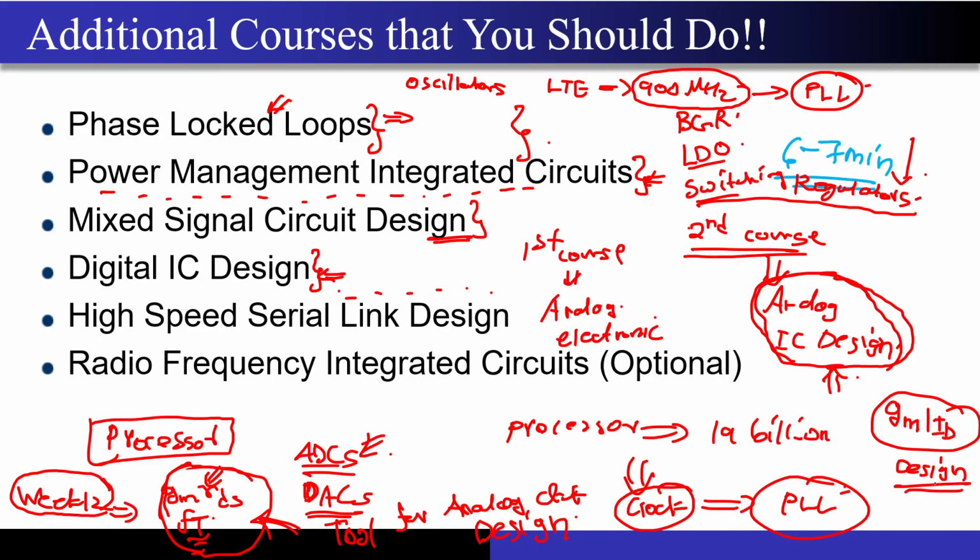Correct? Please have a clear cut understanding of this. At least I want you to get a feel of a few numbers like gm/Id and the fT. Unless you get a feel for these numbers, it will become very difficult to design good circuits.